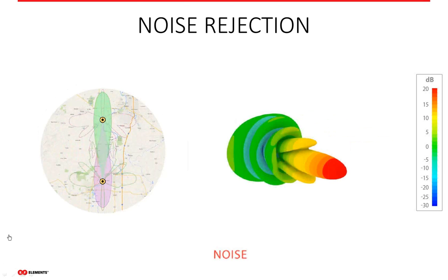The same thing happens if we look here. We're looking at what parabolic dish antennas look like. Parabolic dish antennas are often really misunderstood, because they have such high forward gain, which gives them really narrow main beams. It's thought and understood that this narrow main beam is the greatest source of isolation for the antenna. And this is true. However, it's really not taking into account the huge and very complex side lobes of parabolic dish antenna technology. If we look here, you can see that the side lobes are huge.